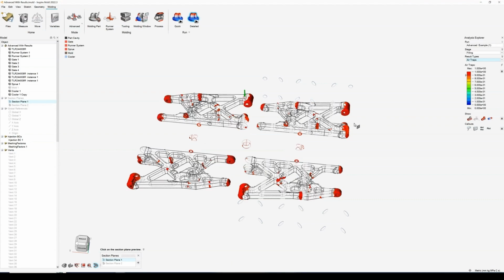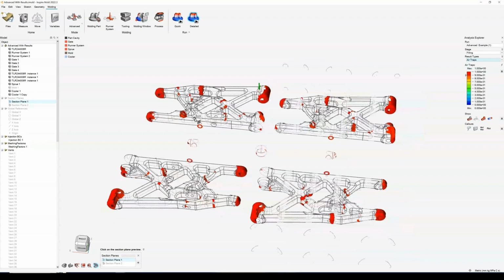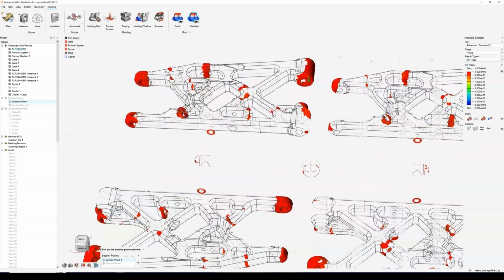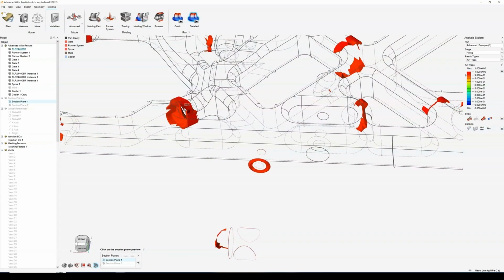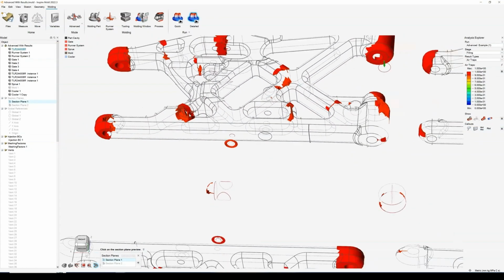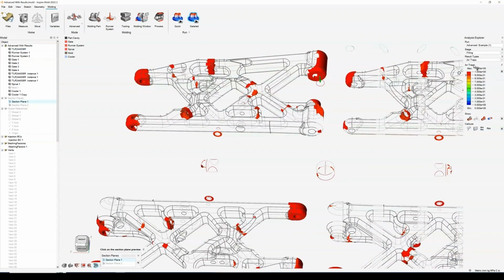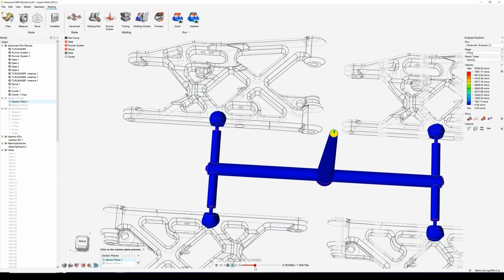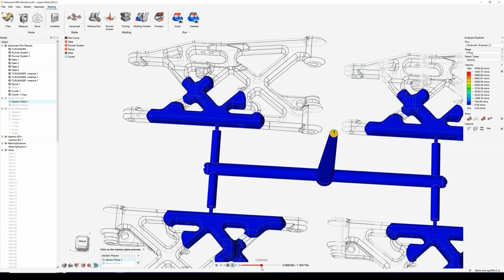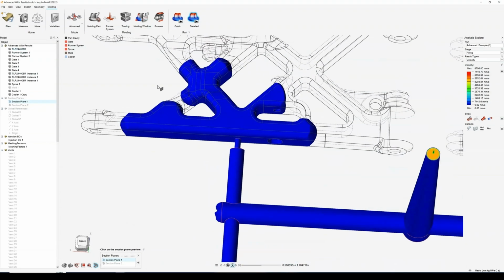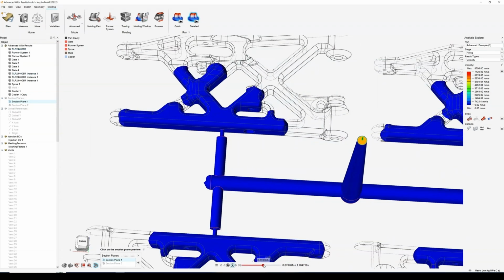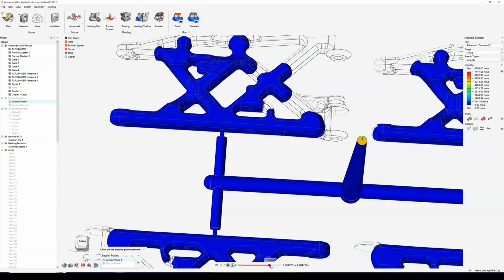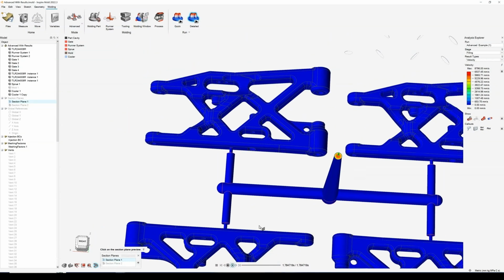You can start to look at air traps. So here we can see air traps. Maybe I haven't vented this very well, but you can see here where we're getting quite a big air trap. You can look at that and ask, what's happening there? Let's go back and look at how the material's flowing at that point. Here we're getting this trapped air where no air can escape. Maybe I haven't had any venting. Maybe that's a venting location that's needed, and we can start to see that.